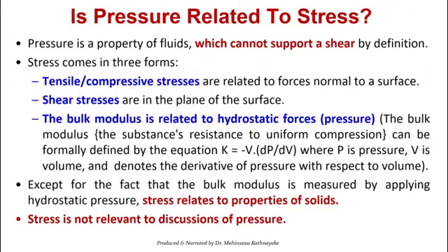But there is some relationship between stress and pressure in another way. In fact, stress is not relevant to the discussion of pressure, but sometimes we use strain. There is a relationship between stress and strain, you know, and strain also has a relationship with force. So force has a relationship with pressure. So we can sometimes use strain as a measurement of force and pressure. So in that case, when we are discussing strain gauges, there is some relationship, but totally, stress will not affect pressure. So you have to clearly understand that part. Don't misunderstand or confuse stress and pressure, right?